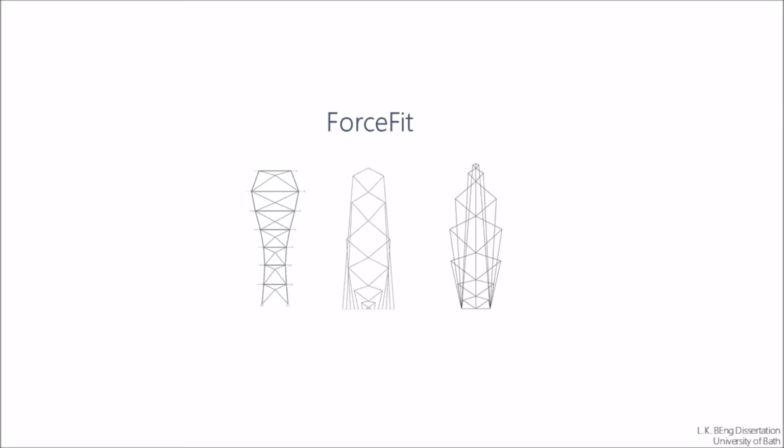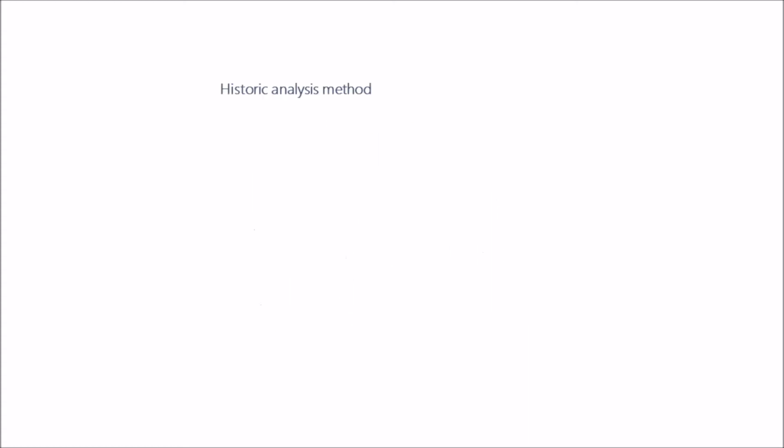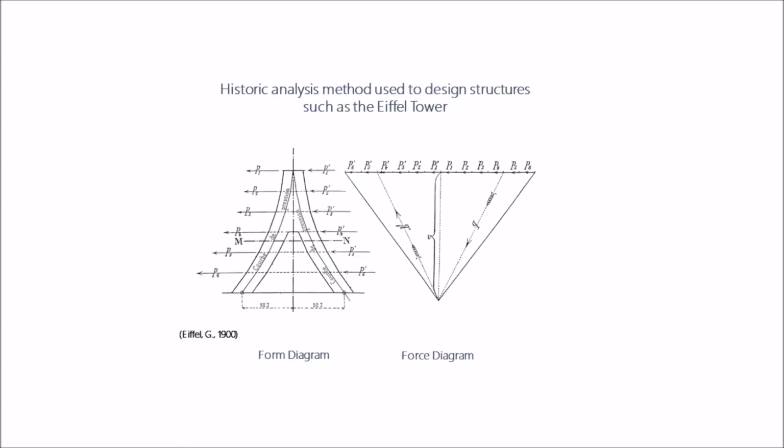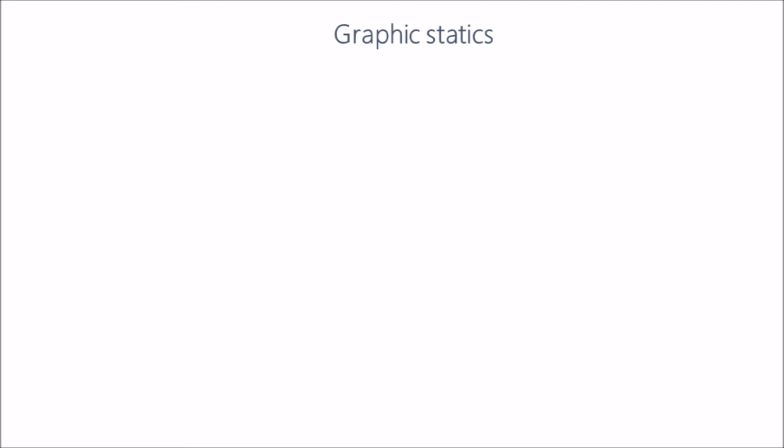This video will introduce ForceFit, which is an educational design exploration tool that makes use of graphic statics. Graphic statics is a historic analysis method which assesses equilibrium and determines internal forces within structures. To complete analysis using graphic statics, two diagrams need to be drawn.